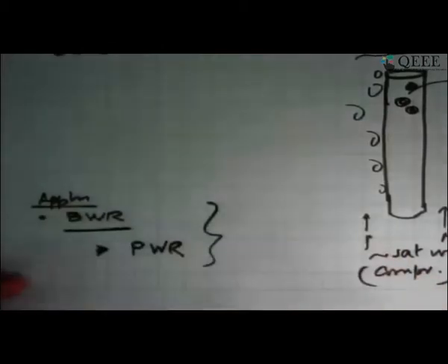So you have avoided boiling in that type of a reactor, and those type of reactors are called pressurized water reactors or PWR. And then this water is taken out to another vessel where it is flashed, you get saturated vapor, and that vapor then drives the turbine. So there are two different technologies which practically cover almost all the nuclear power plants that are operating in the world, a BWR or a PWR. Here there is no boiling, and here boiling does occur.